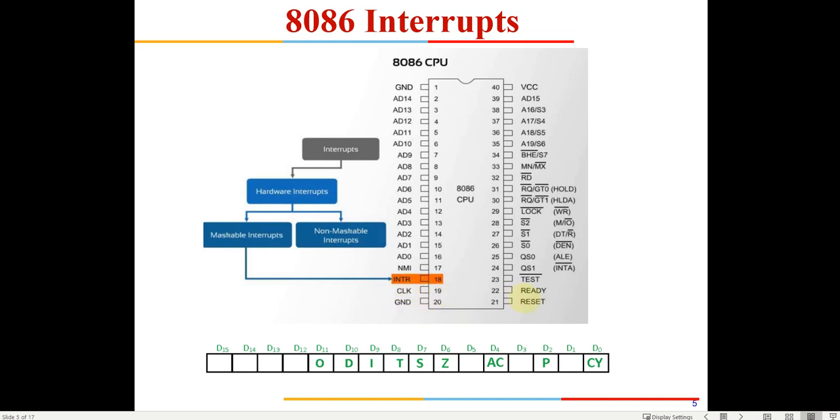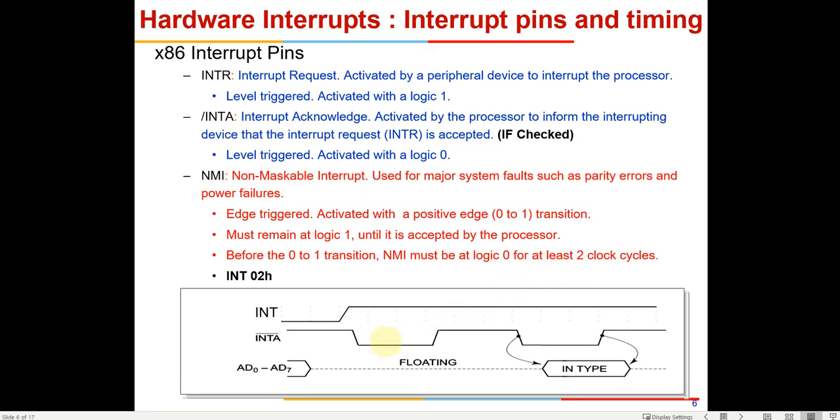We learnt about one interrupt acknowledgement also, right? There is an interrupt acknowledgement pin available here. So the interrupt acknowledgement will go low initially, whenever there is an interrupt coming in. This will tell the IO device, okay, I have received your interrupt signal. You be ready to tell me now what is the interrupt which I have to service.